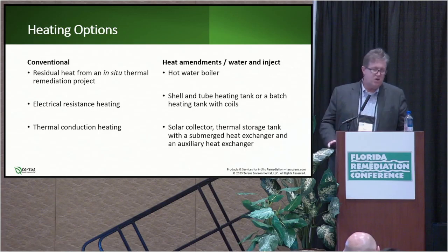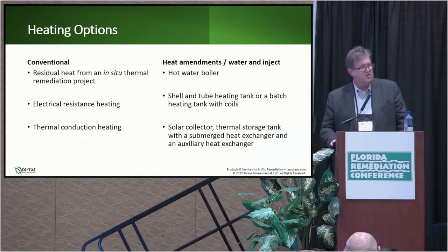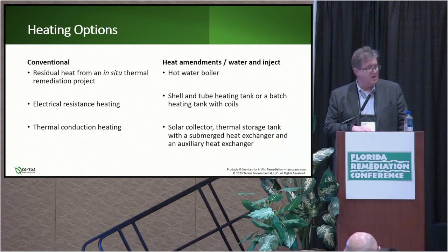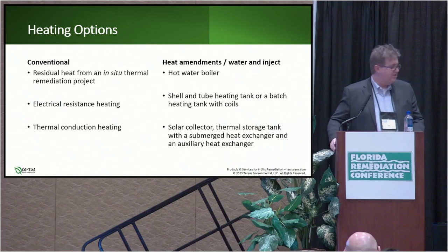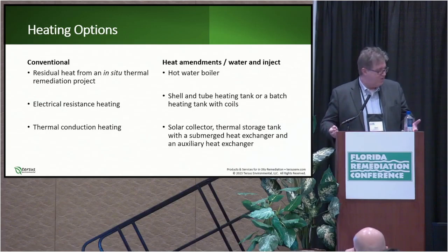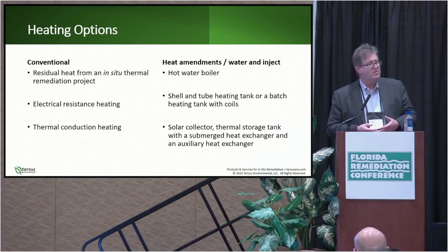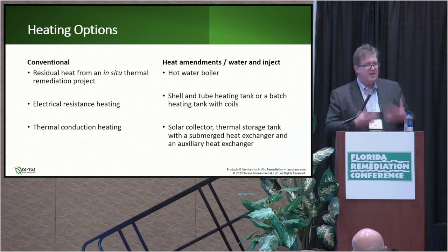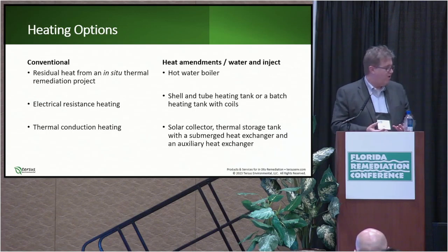We at Tersus, in 2020 and 2022, did a significant number of projects where we went back to where they did electrical resistance heating at sites. The aquifer had cooled back down to ambient conditions, and they still had contamination, and so they injected donor at that time. If they would have injected donor at the beginning, down gradient, or even after the aquifer starts to cool, they could have already taken advantage of that system and of all that money that they spent on putting that energy in to heat that aquifer.